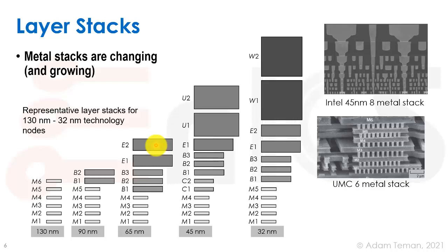The reason that we can do that is, as we remember, we try to make standard cell libraries only with metal 1 inside. In fact, in newer processes, we might have only what they call metal 0 inside. So as long as we don't go up past the initial layer, the X layer, and all of the flavors of the backend flows will have at least one of these X layers, we don't need to differentiate between what the higher layers on top of them are, and then we can provide one lef for our standard cell library and one lib, etc., regardless of what the higher metal stacks are.